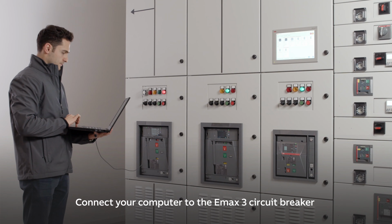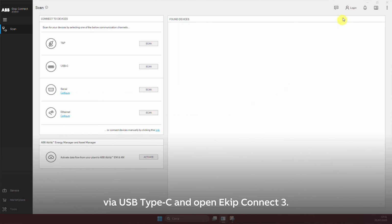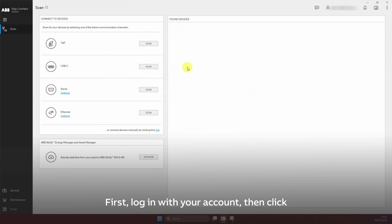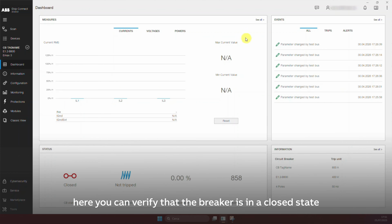Connect your computer to the Emax 3 circuit breaker via USB Type-C and open Ekip Connect 3. First, log in with your account. Then, click the Scan button under the USB-C option. The breaker dashboard will appear. Here, you can verify that the breaker is in a closed state and that no current is flowing.